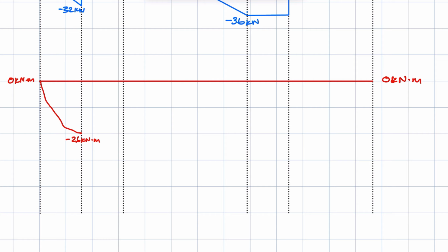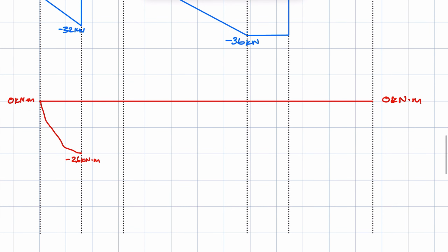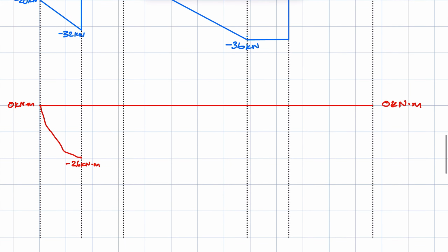And then bending moment at C, which is our maximum bending moment above the zero line, is equal to what? 10 kilonewtons. We still have a UDL in this portion of the beam, so what we do is you continue the parabola below the zero line. So you're going to continue drawing. You already have this portion of the parabola, so now you're going to continue.